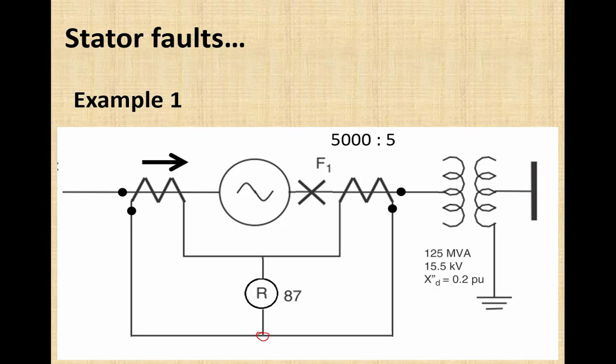According to the subtransient reactance and the given value of voltage, we can calculate this fault current, and that will be 23,280.95 ampere. There will be no counterpart in the second primary. Here there will be no such fault current to the primary of this CT. So that's why we have this current only in one CT primary. So on the secondary side, we will get a current of 23.28 ampere, which will take this path.